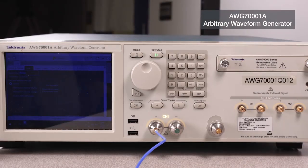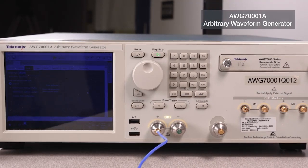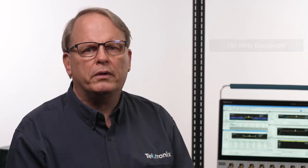Alex? Here in our lab setup, we have a Tektronix 6 Series B MSO as our acquisition hardware and AWG 70,000 arbitrary waveform generator as our source, which is producing a single NR carrier at 3.5 GHz center frequency with a bandwidth of 100 MHz. It's an uplink signal with 30 kHz SCS, 256 QAM, 11.5 dB OFDM PAPR.